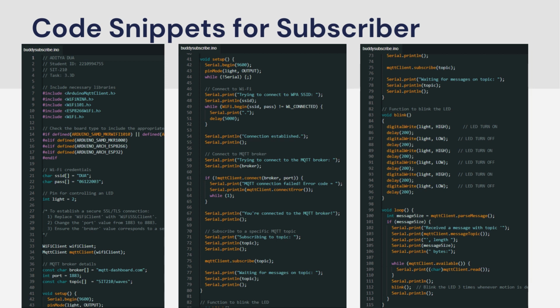Wi-Fi network credentials, that is the SSID and password, are declared in the code to connect to the local Wi-Fi network. The LED, which will be controlled on the basis of MQTT messages, is connected to pin 2. For Wi-Fi and MQTT client setup, two objects are created, which are the Wi-Fi client and the MQTT client. The Wi-Fi client is for establishing a Wi-Fi connection, and the MQTT client uses the Wi-Fi client to handle MQTT communication. Moreover, the MQTT broker's address, the MQTT port, and the MQTT topic to subscribe to, SIT210 waves, are also defined.